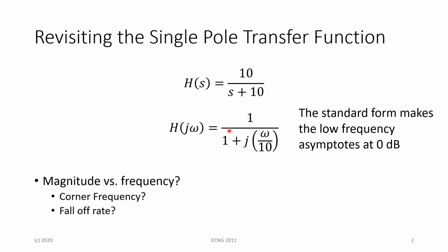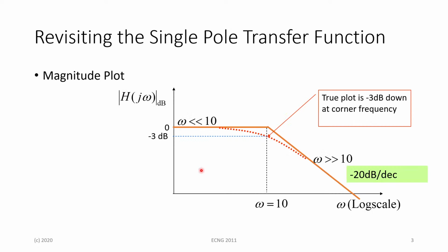We also know that if we did our magnitude versus frequency and phase versus frequency plots, the magnitude plot for anything before the pole would be 0 decibels per decade. But for everything after the pole, it's going to be a gradient of minus 20 decibels per decade. Because we're doing straight line approximations, we just consider before and after. We don't consider this minus 3 decibel change, which is a true plot, because we're just dealing with straight line approximations.